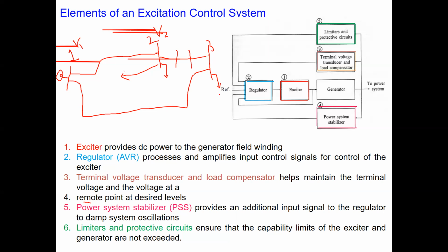Because the amount of reactive power from the excitation system is somewhat lower than with the use of a compensator bank. So let's say, for example, you need something like 300 MVAR. Excitation systems cannot provide you 300 MVAR, right? So that has to be met by your compensating bank only, through capacitor banks or the reactor bank. It cannot be from your excitation system, because let's say your network is completely inductive, right? And your loads are inductive. So just by having one excitation system at the generator, you cannot provide all the reactive power demand in your network, because your line is inductive, your load is inductive, right? So just one exciter system cannot meet all the reactive power demand in the network. So for that, we need separate compensator banks here.